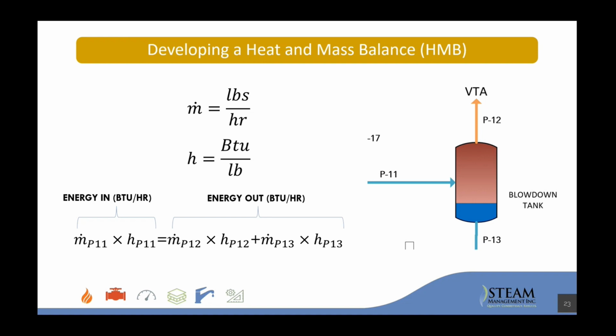Yeah, sorry. We look at hospitals a lot, and they have CUPs, central utility plants. They usually make 110 or 100 psi steam for a typical hospital load. The highest steam users are usually sterilizers at 60, so there's always a steam pressure reduction opportunity, but we just say, bump it down a little bit, see if anything goes crazy.